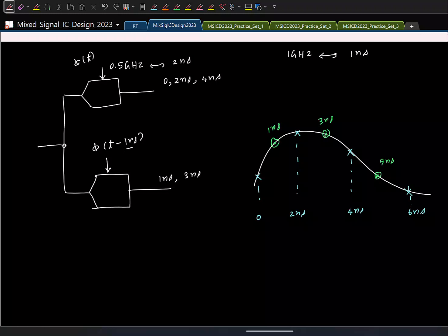So in this way, if you have two ADCs operating at the rate fs by 2, by using these two in parallel and by skewing the time instant for one of the ADCs, you can actually get an effective sampling rate of fs. This principle is called time-interleaving. In particular, this is 2-channel or 2x time-interleaving for obvious reasons. And in practice, to design any high-speed ADC, this is the principle that is adopted.